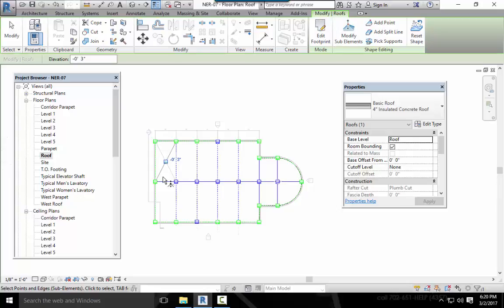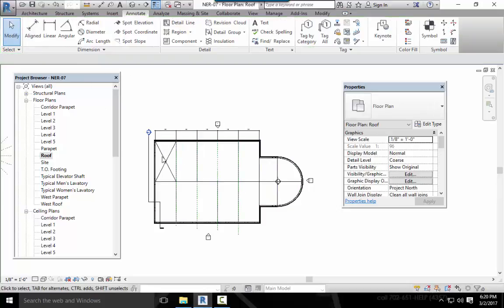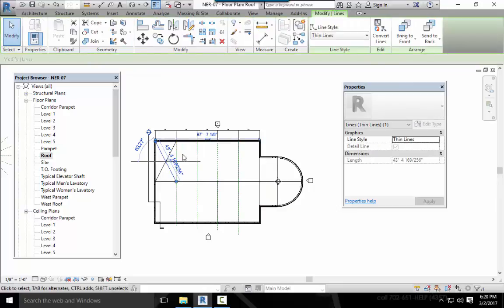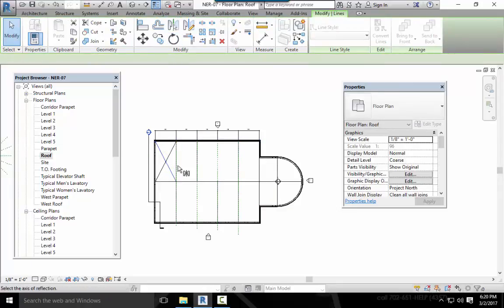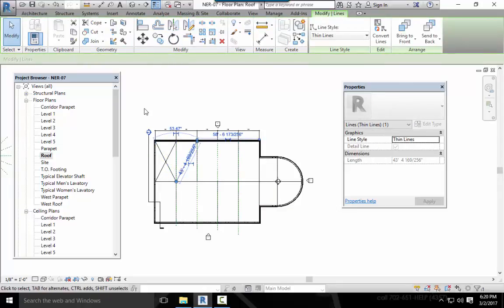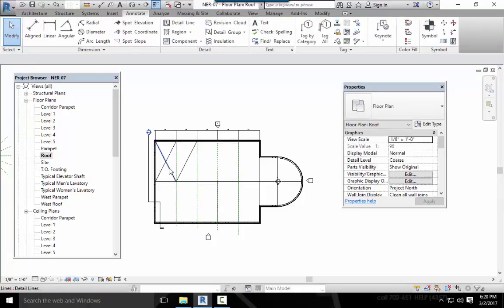So basically, it wants you to continue to add those points until you end up with something that looks like figure 7.16. So I'm going to do that very quickly to show you how to do that, and then you can work through it. So since I have this in place, what I'm going to do now is come out of it. I'm going to select that detail line, and since this really should be very much a mirror, I'm just going to mirror that line.